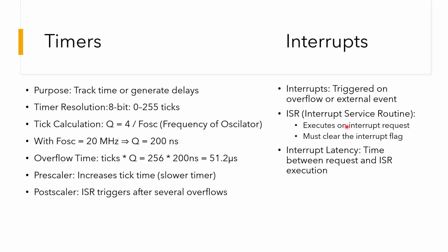Interrupts are used to respond immediately to events like timer overflows or external signals. When triggered, an ISR or interrupt service routine is executed. It's important to manage flags and consider interrupt latency for responsive design.